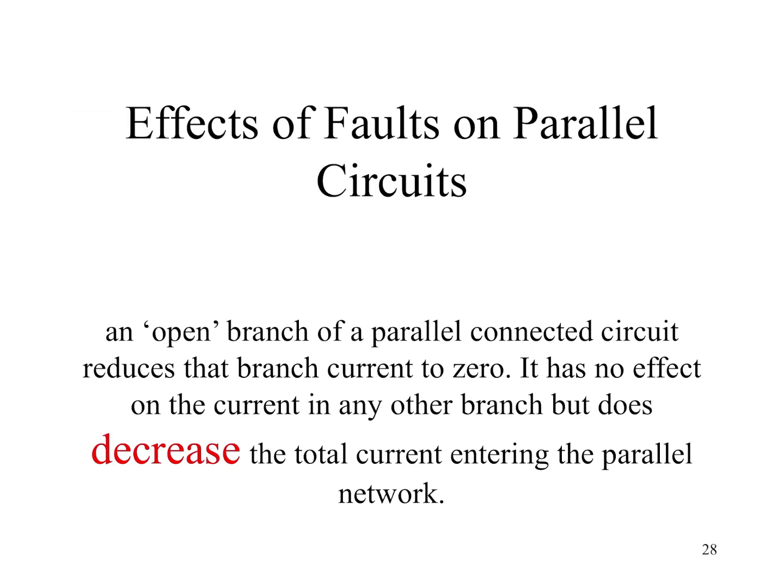So next we're going to look at the effect of faults on parallel circuits. And one thing to note right now is that when it comes to faults in a purely parallel circuit, we never investigate a short circuit. The reason is that when we're talking about a short circuit in a parallel circuit, the theoretical result would be infinite current. So in a calculation, you would conclude that you have infinite current, but then the issue always comes down to, okay, with infinite current, what would the ideal source be? And the ideal source, you would say, can supply infinite current while still providing the same voltage.